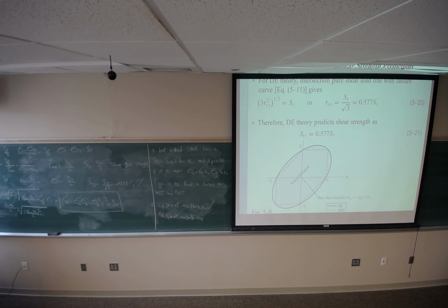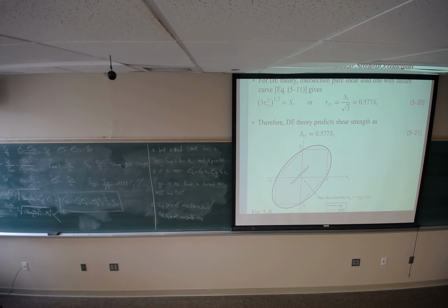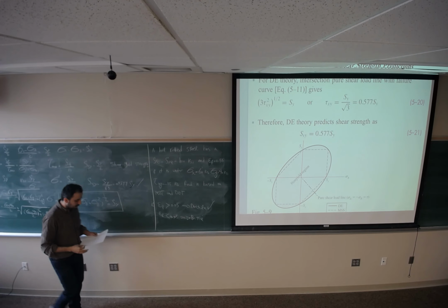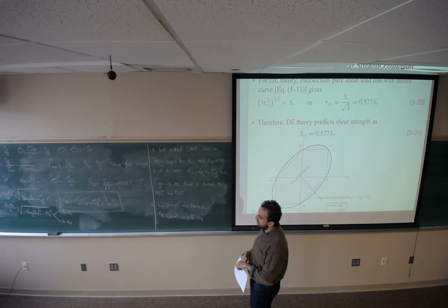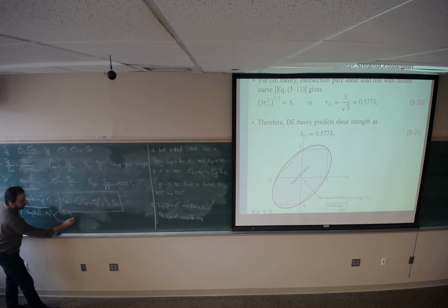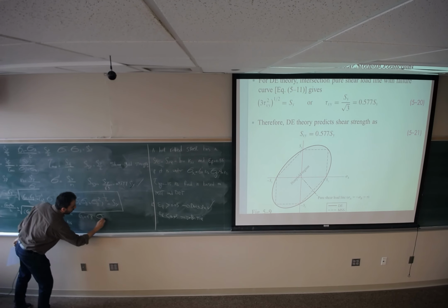If it's negative 15, it should go down. The results would be 68 and 32. So the principal normal stresses A and B are 68 and 32. We have 68, 32, and the last one is 0. So the greatest, sigma 1, is 68, and the smallest, sigma 3, is 0.